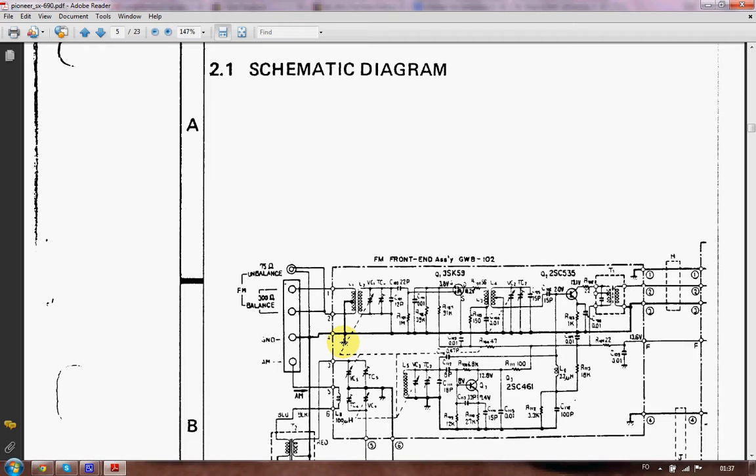When you get into your circuits, your given voltages are whatever they imply to be in relation to ground. So that's why you want to have your negative probe on ground when you try to look for given voltages.